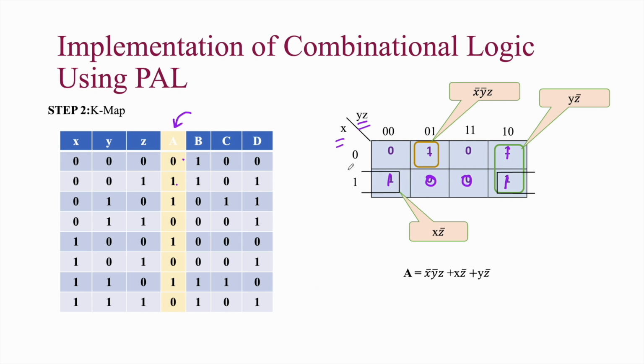Now we have to group. This is one possible grouping of taking these two together, highlighted with green color, and this forms one group. This other one cannot be grouped, so we are forming it separately. When we consider these two corners, the X variable is common to both these minterms, therefore we write X. When we consider column wise, we have 0, 0 and 1, 0, which is nothing but Y and Z. Z is common, in the form of 0, therefore we can write Z bar.